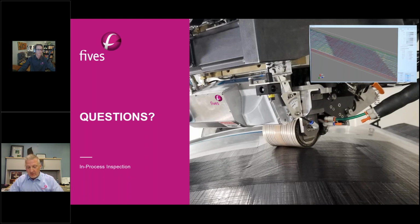So we are in a production environment with this on a machine today, and as of today, I don't know 100% for sure, but we've not had issues with that, mainly because our prototypes have the exact same FOD mitigation that off-the-shelf laser line triangulation has, right? So the packaging and the lens protection does not change, and that's proven technology. So no, we will not have impacts from any external material.